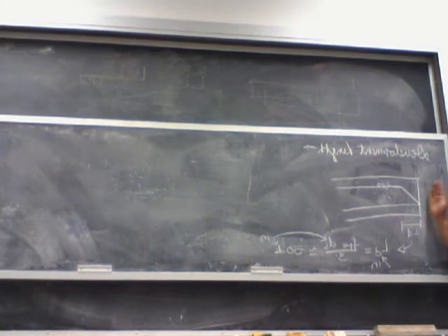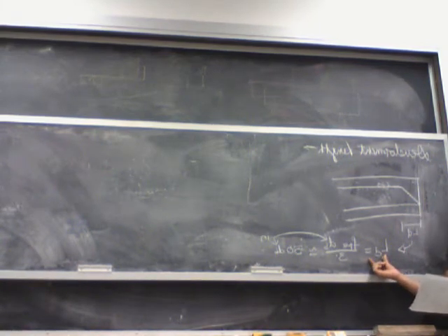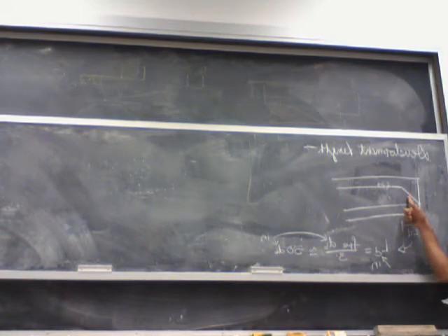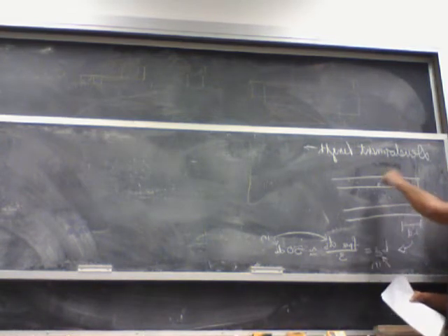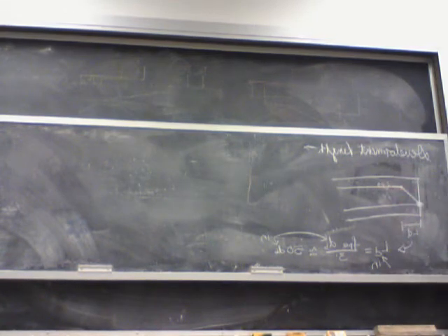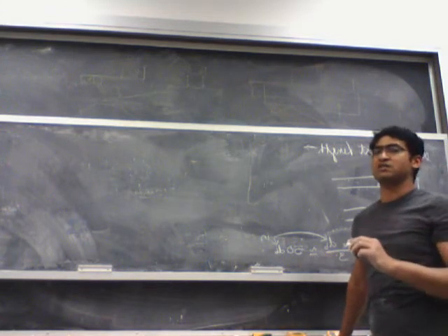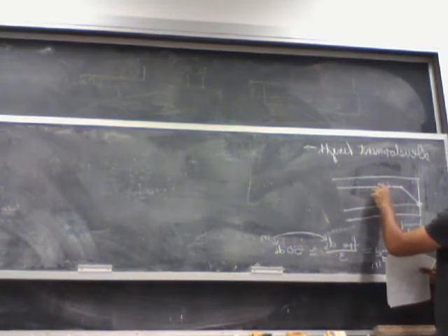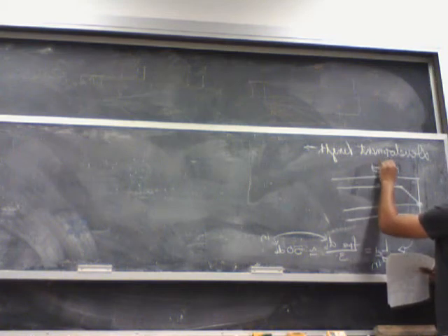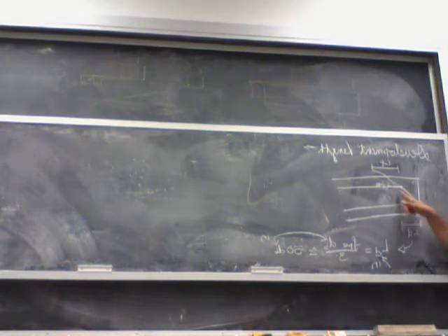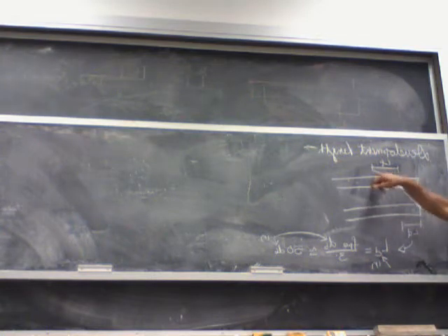So what it is simply saying is from the end of the beam until a length of LD, the stress in the strand is actually less than FPS, and it increases linearly from 0 at the end to FPS at a distance of LD. Now let's say if I increase the loading on this beam further, stress in the strand will keep on increasing. It will keep on increasing until it reaches the stress of FPS, where FPS is the stress in the strand at the nominal moment capacity of the beam. So if I want to go from FPE to FPS, I need an extra length, which is defined as LF. So LD is the length to go from 0 to FPE, and then LF is the length to go from FPE to FPS.